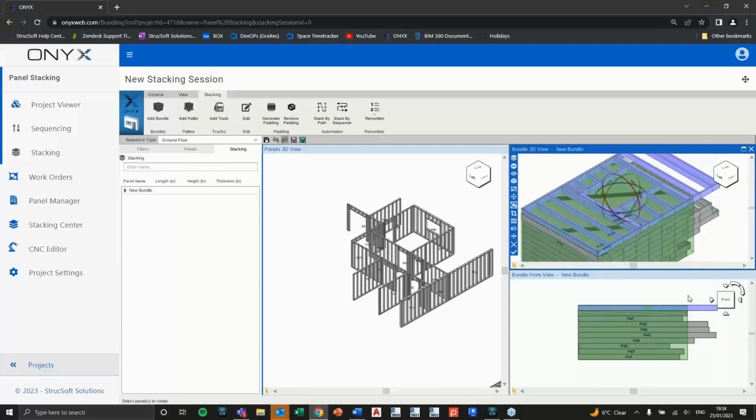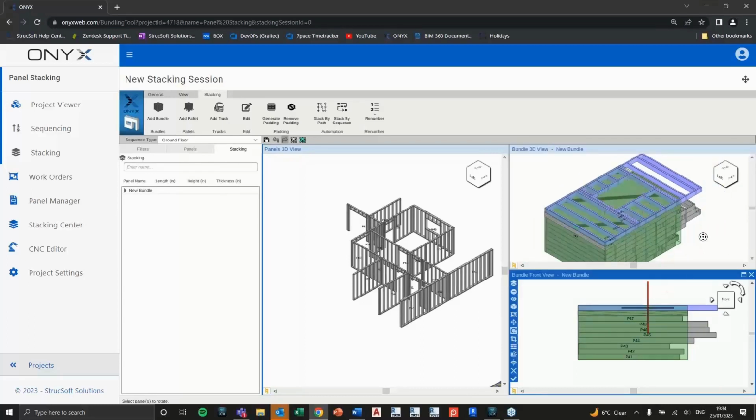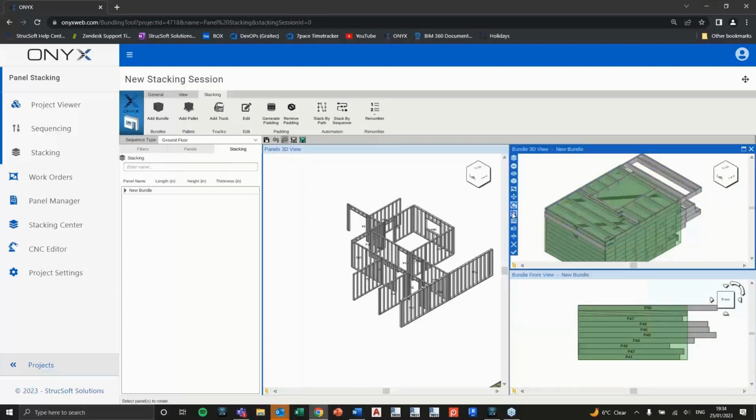Okay. I should really be working in this elevation view if I'm going to do it that way. It's absolutely fine. Okay. So we have the shrink option. This is the tool I was referring to earlier on when I said that this container doesn't quite match the size of these elements. We can shrink wrap these elements using the shrink option, and it will stretch this container to fit around the extreme element, so the largest element, and make sure everything's contained correctly.